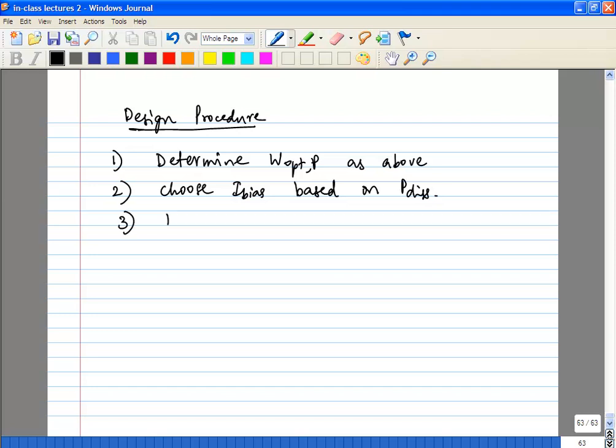Next, you're going to determine LS. The thing to remember is, obviously I have not put in the length of the transistor. I'm assuming that you're going to use minimum length because you want maximum fT, and you would normally want to do that if you want to hit minimum noise figure. Once you have these two, you know CGS, so then you can calculate LS, your source inductance, to match, because once you determine I bias and W opt, you already know your omega T. Omega T times LS is 50 ohms.